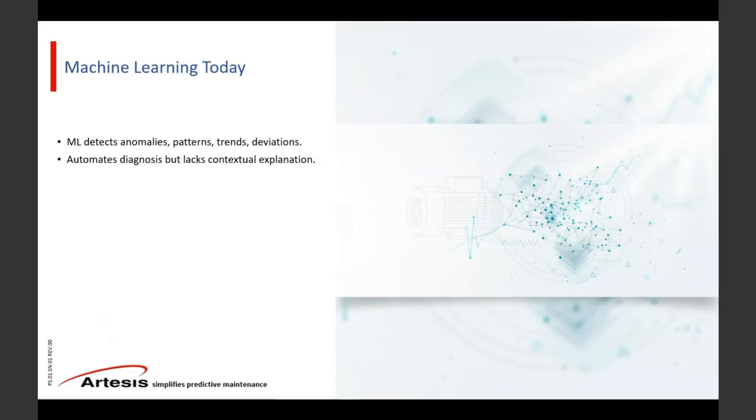It can recognize repeating patterns in signals, and it can track fault progression over weeks or months, and it can constantly compare today's behavior against a learned baseline, even when the equipment has a lot of operating variation nowadays with VFDs and load changes and fluctuations. So in practice, our machine learning-based system already automates a big chunk of diagnostic workload.